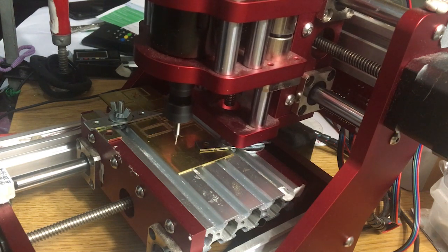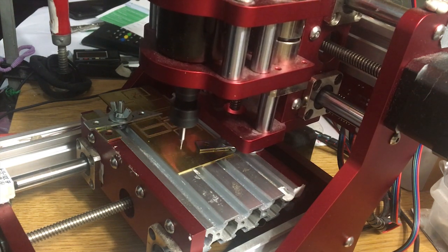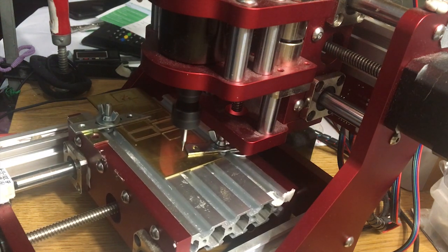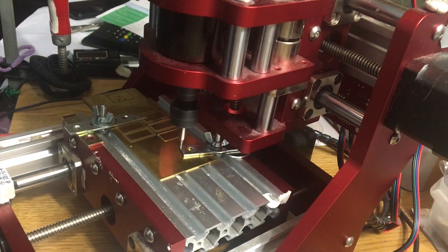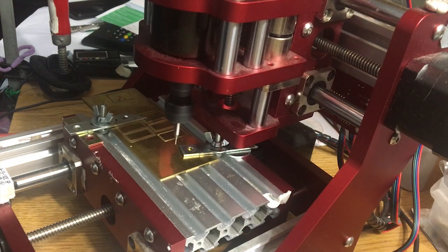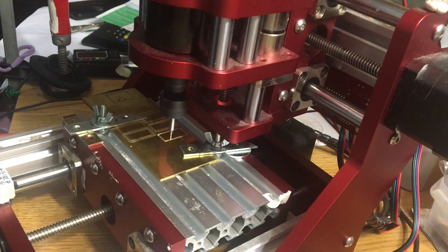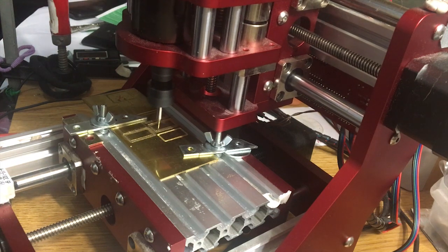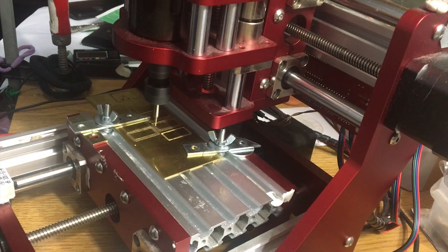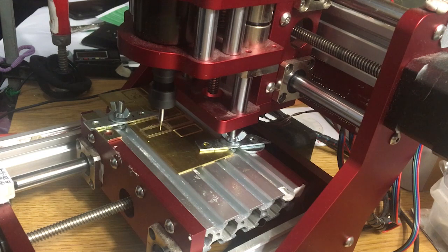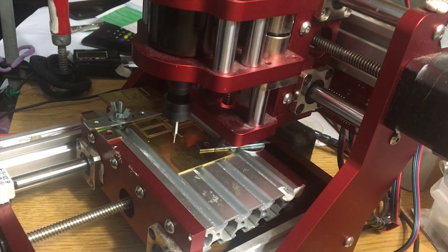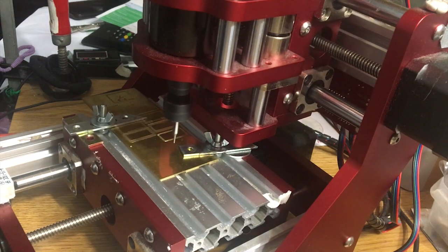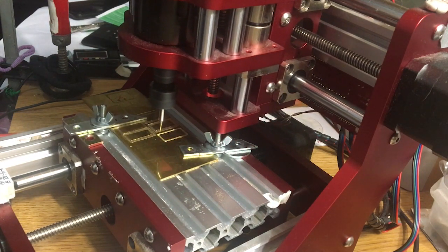The depth used was 0.01 millimeters every cycle to protect the bit, because brass is a hard metal. I ran my first video in order to save the repetitive cycle. At this point, I stopped the video to continue in next part B.